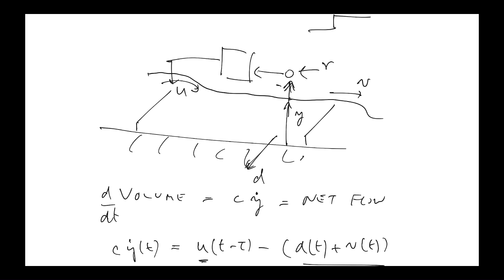Okay, so last time we looked at what can be done with just a proportional gain controller. Okay, we saw that proportional gain control can at least stabilise the system. All right, but there's a limit to how much gain you can have in the controller because of the delay. All right, so the fact that there's delay here, the effect of changing the inflow on the water level downstream is only seen after some time, and because of that delay, there's a limit on how large the gain can be.